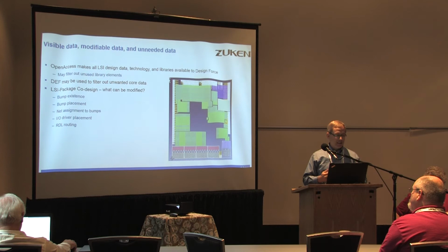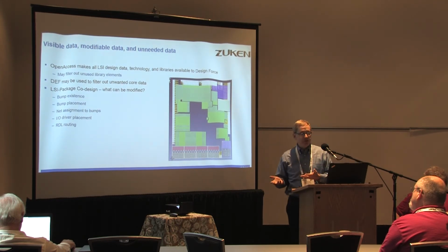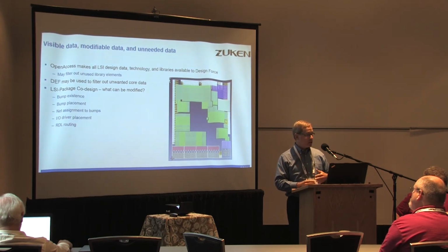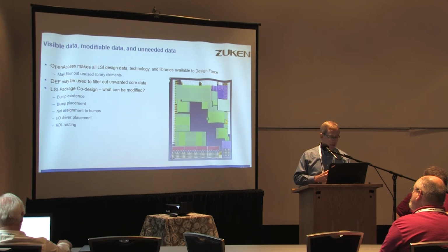And then when you're doing LSI package co-design, you will need to decide what you are going to allow to change. Most people will typically just allow you to add and delete bumps and do net assignments to those bumps, power and ground net assignments to the bumps. But there are some flows in use today where they will do I/O placement, create the I/O pad ring in the context of the package, and do the bump assignments and the RDL routing in Design Force.